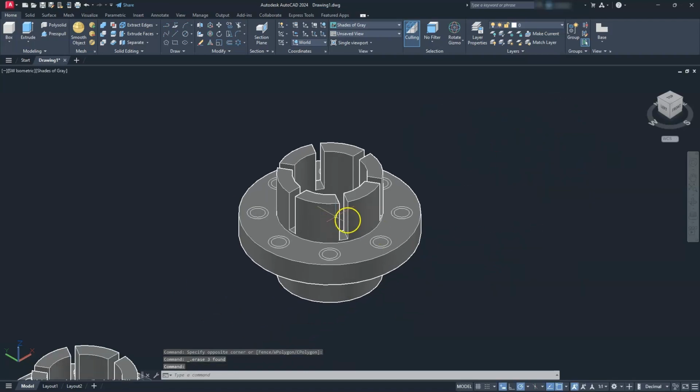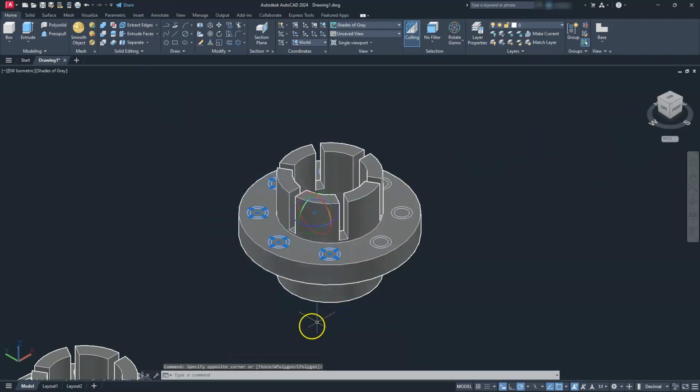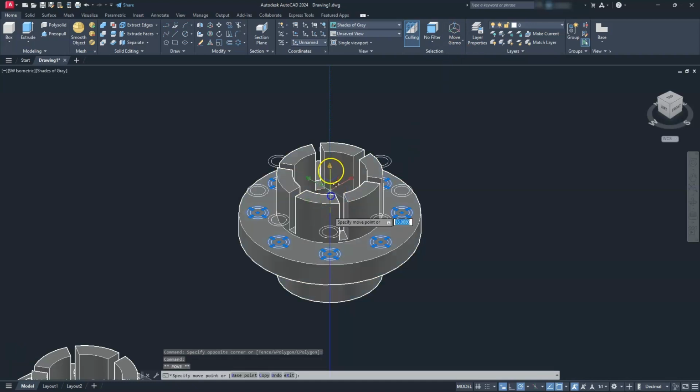And now I need to do some manipulation here. Kind of like what we did before, if I put a window around these objects here, and I'm using this blue window since it works a lot quicker, I can use this move gizmo, select the blue axis, come up, and then tell it that it needs to go up a height of 2.